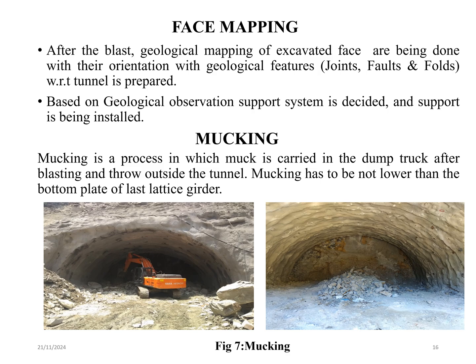Face mapping. After the blast, geological mapping of the excavated face is done with its orientation and the geological features, including joints, faults, etc., with respect to the tunnel. Based on geological observation, the support system is decided and support is installed.